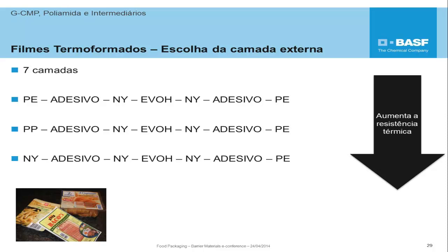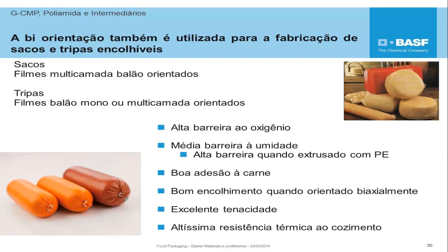Slide 30. A process that is used a lot with polyamide film is the process of biorientation. The examples we have here are cases or bags with bioriented multi-layer blown film. That process orients the polymer in the machine direction and also transversely, depending on the blowing ratio that stretches the bubble or tube radially. This relationship of longitudinal and transverse stretch defines the proportion of shrinkage of the film and packing. And so we see the examples, shrink bags mainly for packaging of cheese and meats.